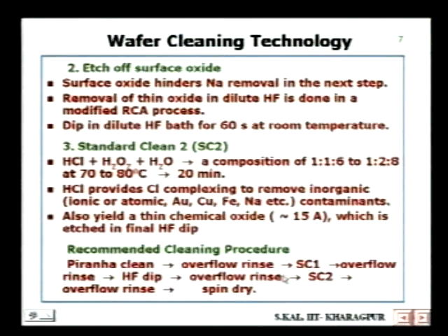Then again overflow rinse. Then SC2. SC2 is the HCl, H2O2 and H2O clean. And then again overflow rinse. Then spin dry. So after each step we use DI water rinsing, which is known as overflow rinse. At the end, we dry the silicon wafers using a spinning technique, known as the spin dry technique.